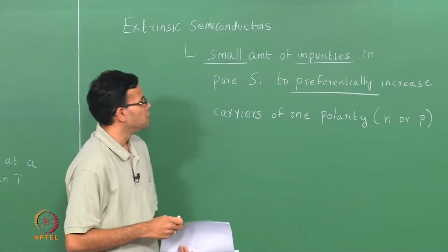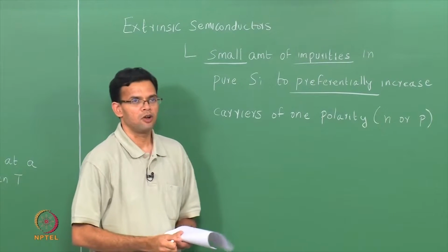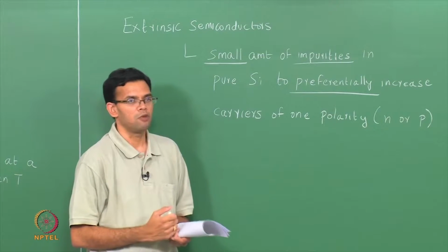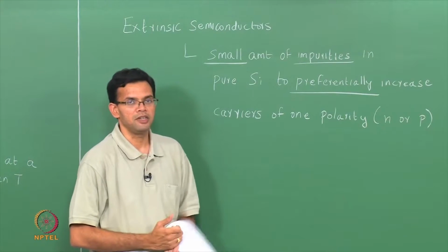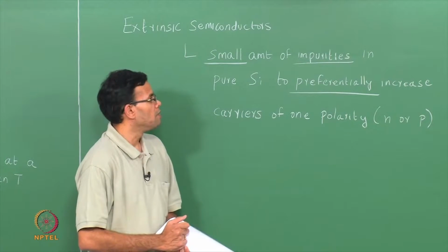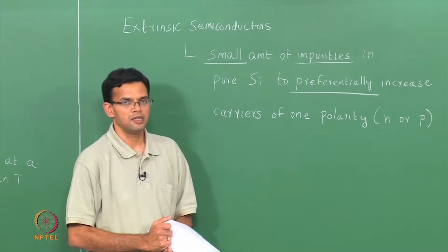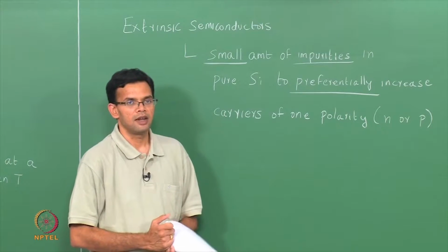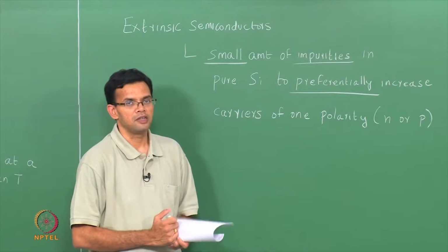When we think of impurities in the context of metallurgy, we usually think of small amounts of unwanted materials that are there because of some processing problem. But in the case of semiconductors, impurities are carefully controlled materials that are added to your pure semiconductor to change the conductivity.